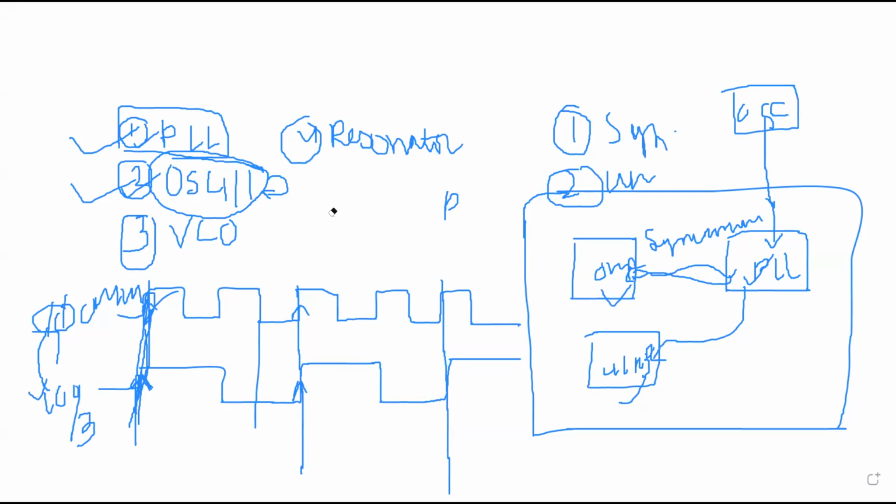If the source for this 100 megahertz and 33.3 megahertz is the same, can they be said to be synchronous? No, actually that is what I was going to correct. We have to see that the source should be the same and the phase difference should also be constant.